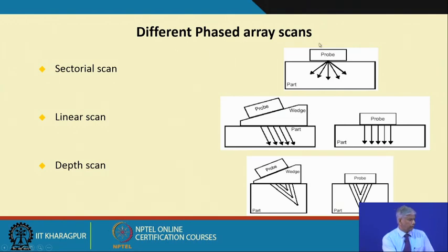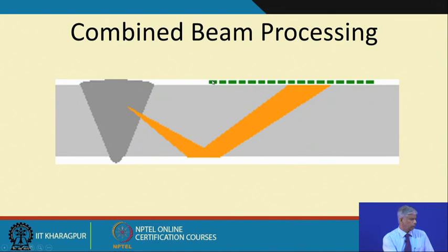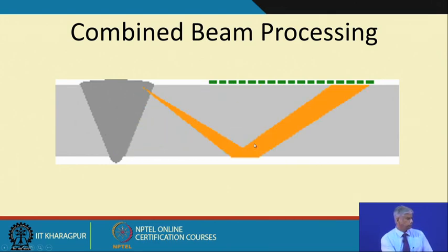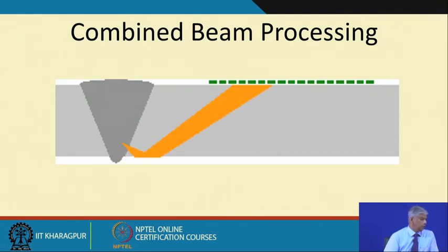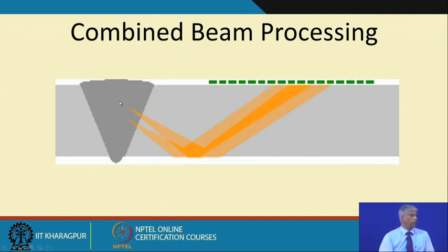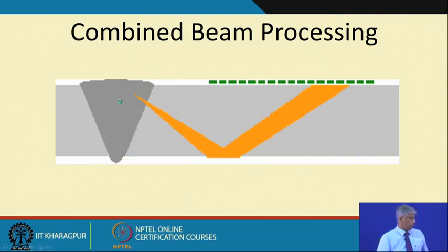So, different phased array scans are available. Okay. So, this is a weld defect. So, we can do that and so on. Okay. So, the entire depth of this weldment is scanned. Since I am moving it, this angle is not changing, but as opposed to this, we can scan the entire surface, and this is what is essential when we do the weld defect scanning. And so, I can identify if there is a reflection here, I can identify where the spot is. So, such arrangements are there.